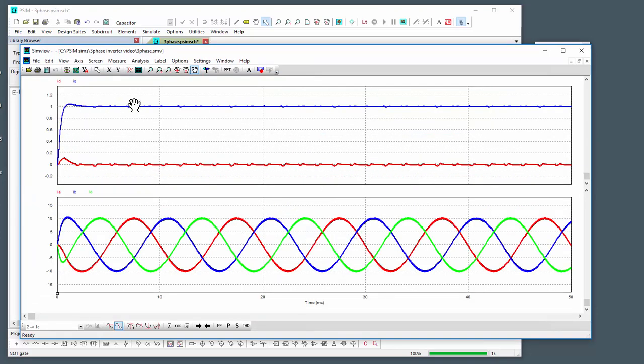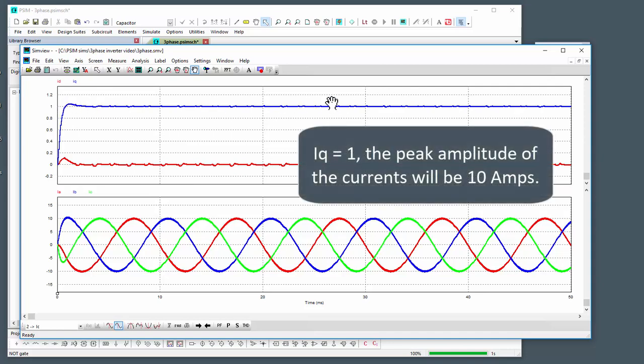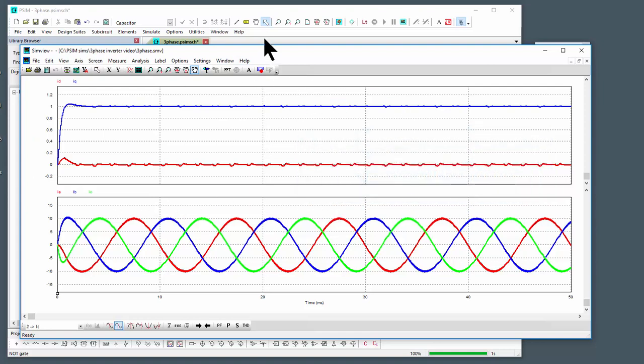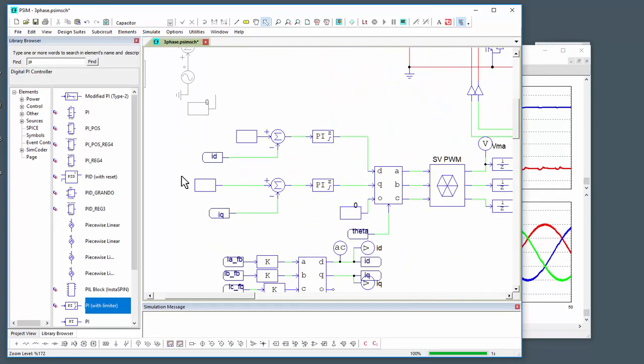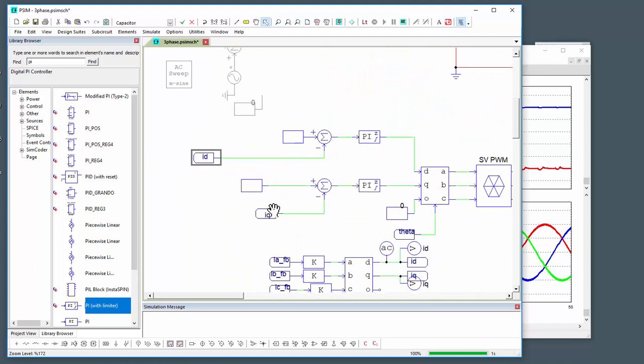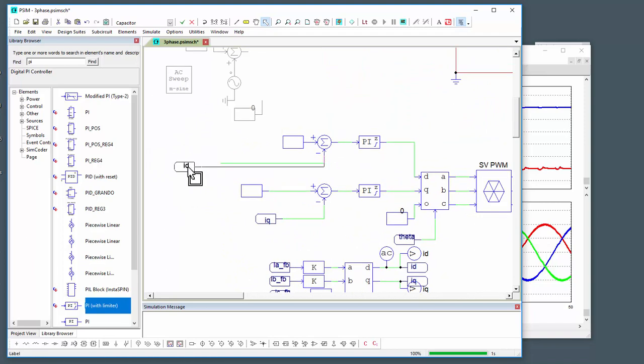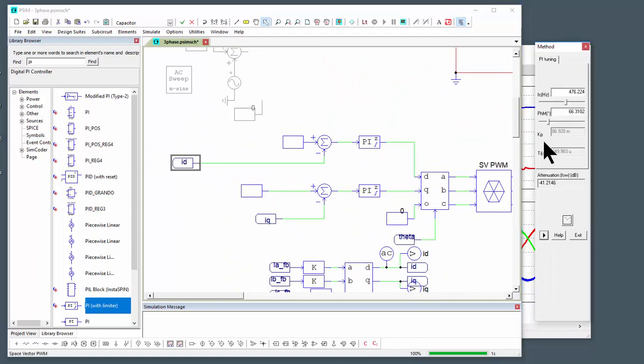And then we would gain this because we did that 1/10 attenuation. So this is now equivalent to this 10x. So the peak of this. Okay, what else can we play with here? So we can actually confirm that that's the case. That we can confirm the SmartCtrl design numbers here for cross frequency and phase margin.